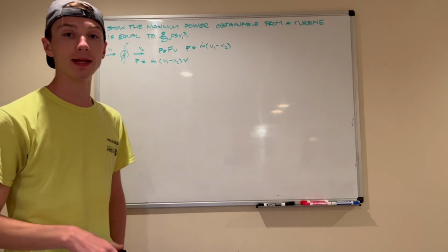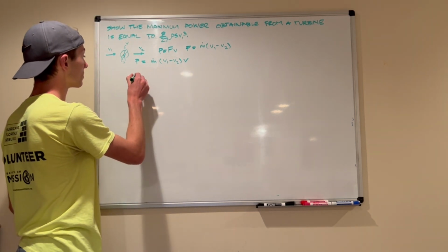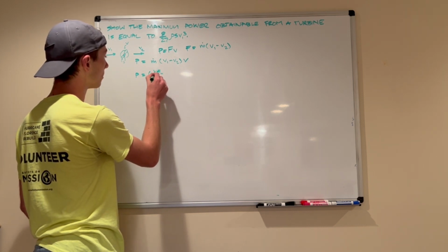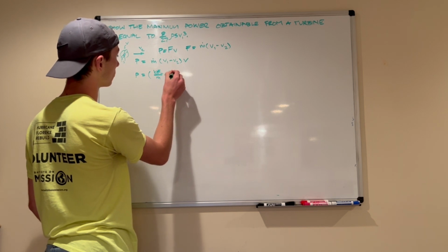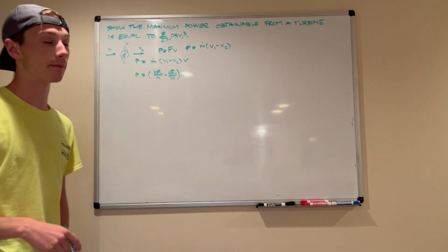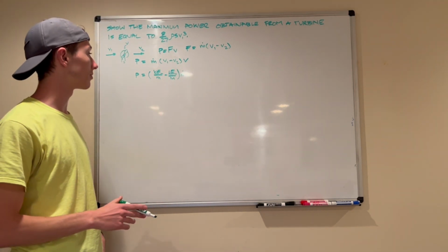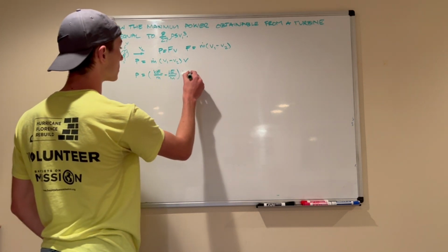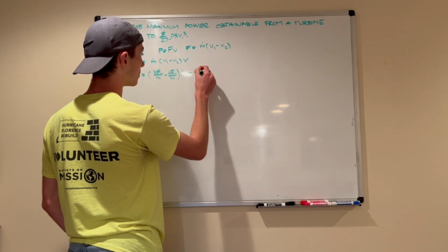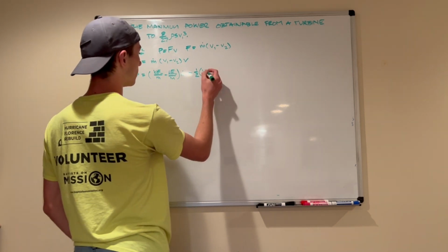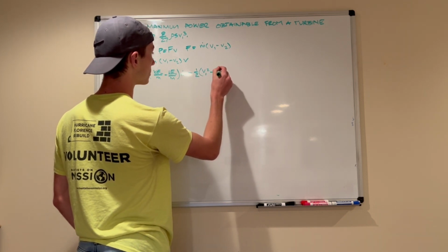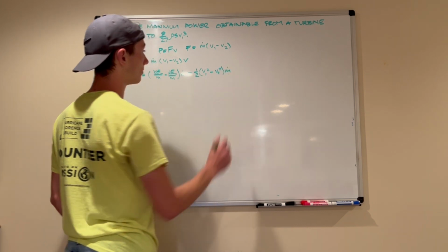We also know power in terms of energy: some kinetic energy in per mass minus some kinetic energy out per mass, times our mass flow per time. That's also an expression for power. What that comes out to be is 1/2, factoring out the 1/2, times V1 squared minus V2 squared times mass flow.